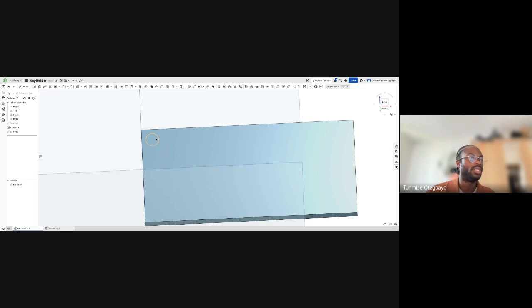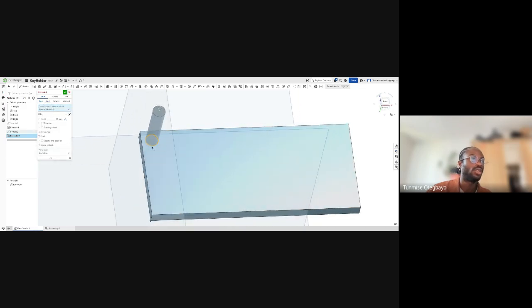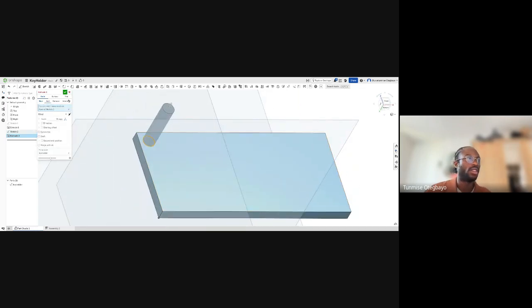Again, all we have is this sketch and this sketch region, but we need to make a hole through it. How do we do that? We go back to the extrude again. If we notice, it says select the face and a region and what to add. If you go over your circle in sketch 2, you can see it's highlighting that circle. If you select it, you can extrude again and set the distance that you want to extrude. But what we notice is this is not a hole. This is an extension on top of it.